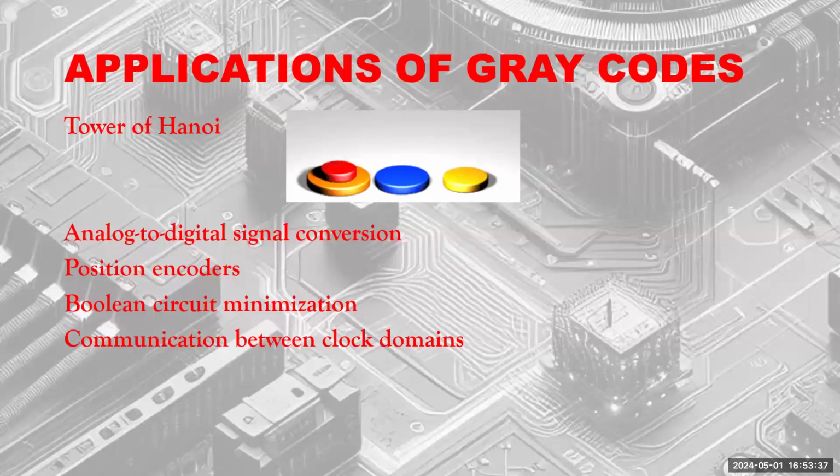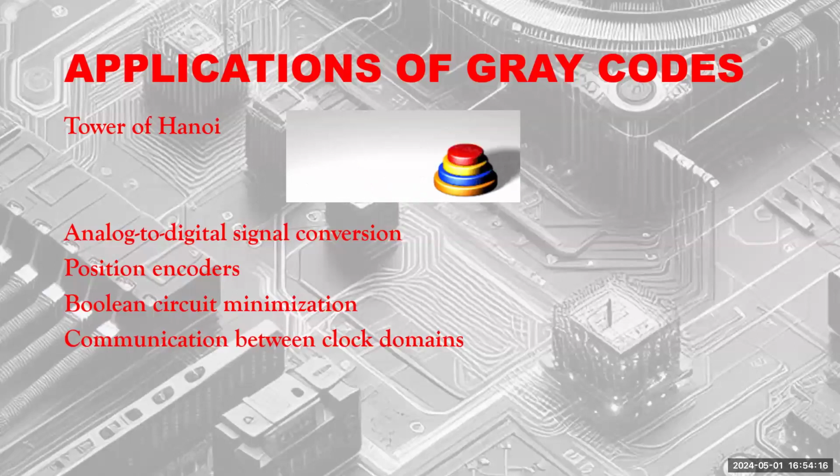For example, one basic way is to blindly assign binary codes. Say state A is 0, state B is 1, state C is 2, like that, without being too thoughtful about it. You assign some numbers and go ahead and design your Karnaugh maps of next state and output based on that. So that's one method. Another method is called one hot coding, where if there are 8 states, you keep as many as 8 bits of state and say 00000001 is state A, 00000010 is state B, 00000100 is state C. One hot, only one bit will be hot at a time. So that's one other coding.